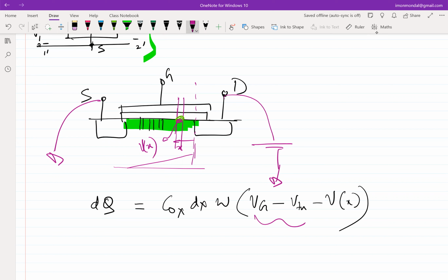Okay, so you are comfortable with this. And why are you not comfortable with minus V of X? So note that this is Vt, right? I can assume that this is Vt here because everything is referred to, right? But we are interested in the charge here. It's a parallel plate, right? I know this voltage, I need to know this voltage. This voltage I am calling it a sliver. So within that small sliver, I have that much amount of charge. The maximum value of V of X is Vt, right? Exactly. The maximum value of V of X is Vt, right?